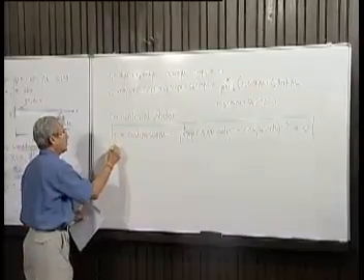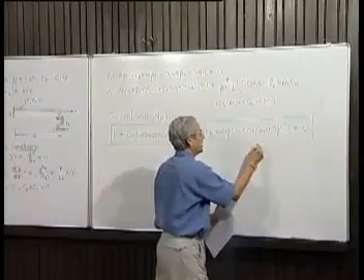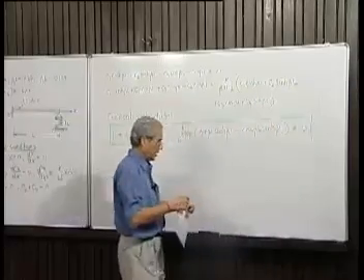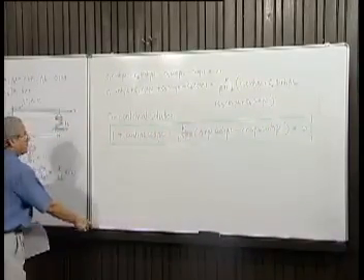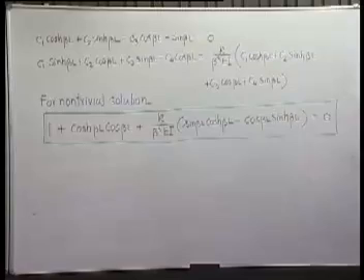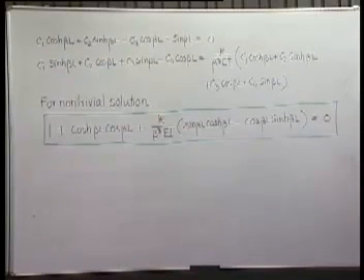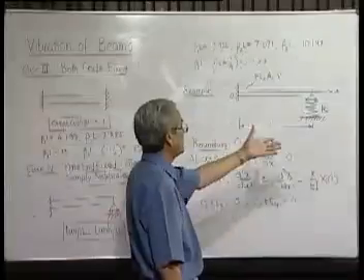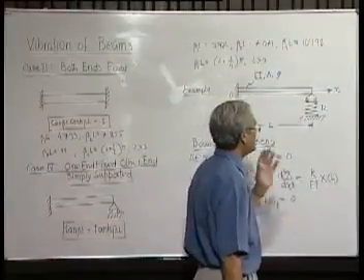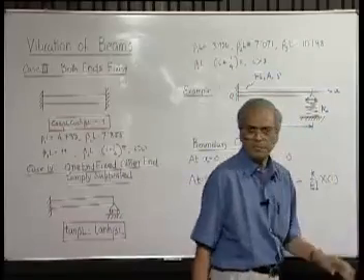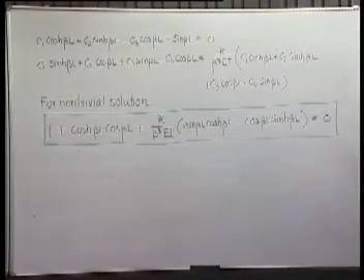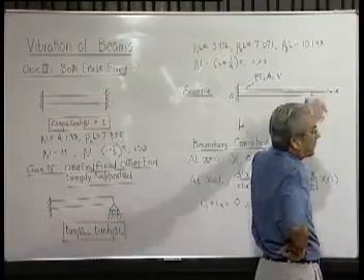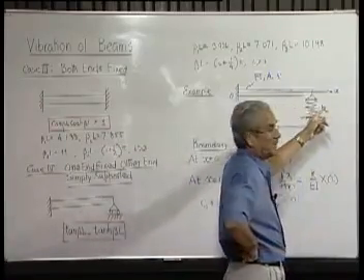This has to be solved numerically, obviously, when all the values are given, and values of beta can be found out, an infinite number of betas like beta 1, beta 2 and so on. So in this case you can see it is no simple matter, it is only possible to solve numerically. We can check some limiting cases. For example, if the spring stiffness is 0, what does it mean? The end is free. That means it is nothing but a cantilever beam.